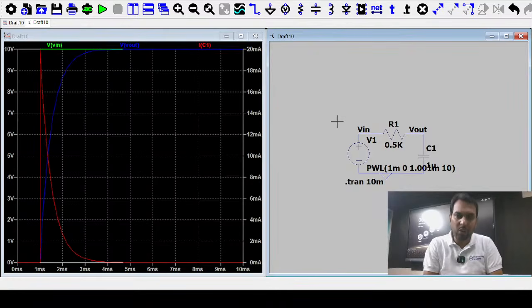On the basis of that, you find that your slew rate is high enough in the circuit design, and that is good. That is 10 volt per microsecond, that is very good. 5 volt per microsecond is very good as per your design specification in an analog circuit. But once you go for the layout, you find that this is not 5 volt per microsecond, it is less than that. So the slew rate is small.